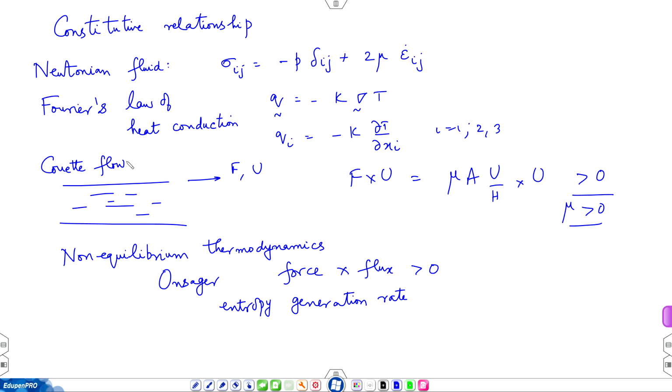So, a model problem that we think of in heat transfer is a slab. So, this is a slab of some finite thickness L, and you apply a temperature difference across this slab, and then Fourier's law tells you that q will be equal to K (T1 minus T2) over L, and the entropy generation.